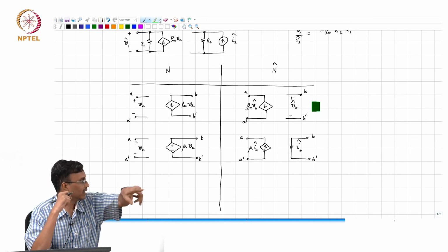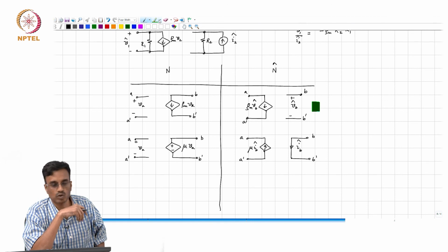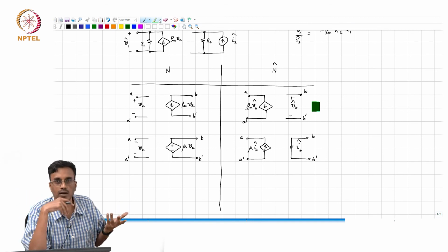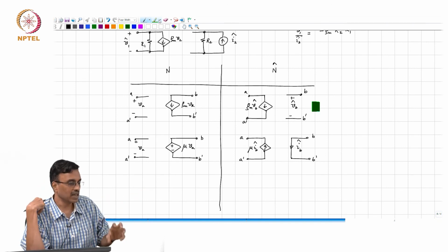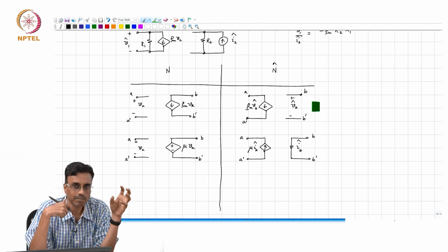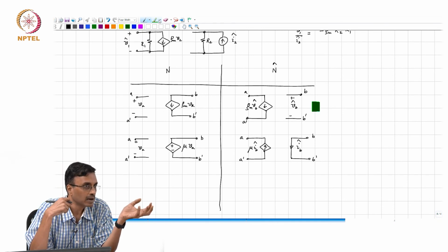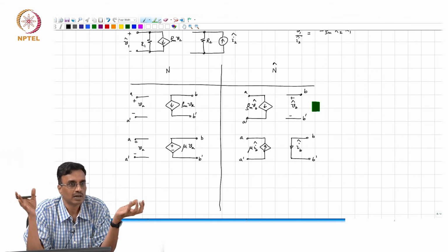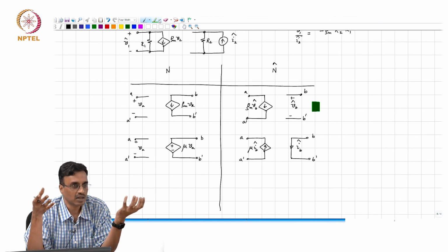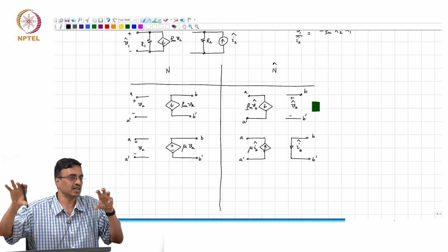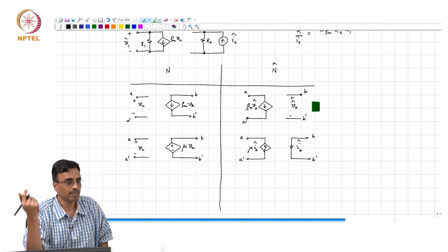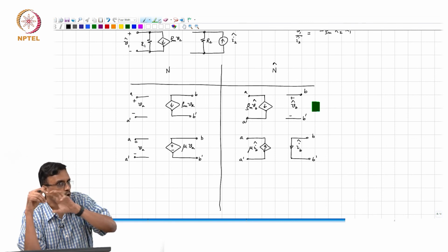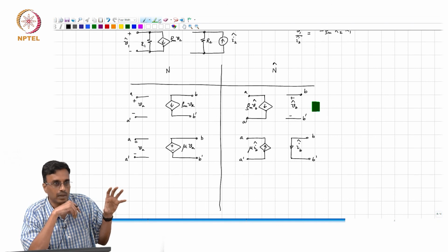Oh, okay. So, I think that comes back to his question, which is, so what, right? We've done all this, so why is this useful? It comes back to the fact that in many practical situations, one is interested in finding the transfer function from multiple sources to a single output. In the passive case, one used reciprocity to advantage. You took the same network, simply interchanged the location of the excitation, and in one shot you are able to calculate all these transfer functions that you are looking for, right?